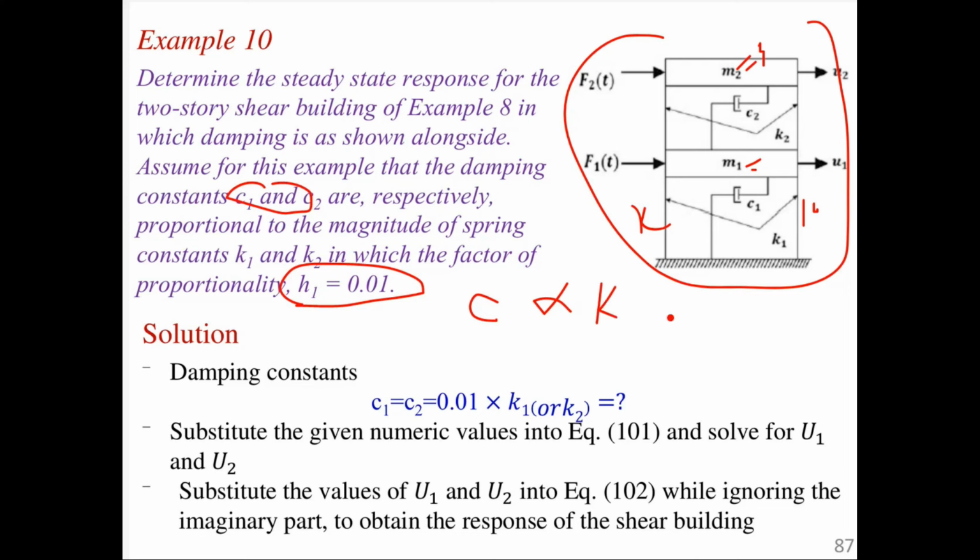Let me just explain the implication or the meaning of this. The stiffness of the structure brings about the restoring force. But at the same time, the viscous damping arises as a result of the inherent characteristic of the material that constitutes our structure. The material and geometry affect the value of K. Remember last semester's discussion? If the material, let's say concrete, is too stiff, then the damping value will also be large. So the damping itself will also be related to the material.